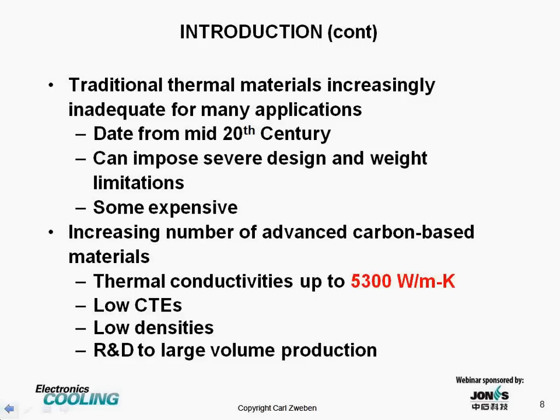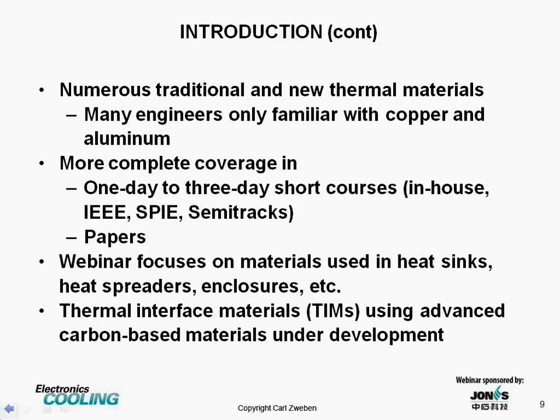These materials offer conductivities up to 5,300 watts per meter Kelvin compared to 400 for copper. They all have low CTEs, low densities, and I emphasize that they are at various stages of development from R&D to large volume production.